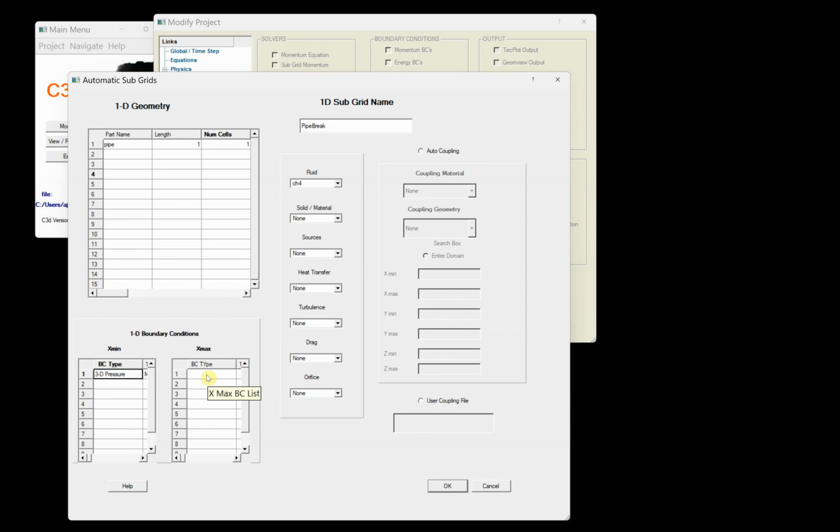And for this, there are several different options on how we do this. We could have it as a surface source coming off of the materials, which would simulate evaporation. I think we want to do that because we're going to follow this with a fire. So we'll double click here.